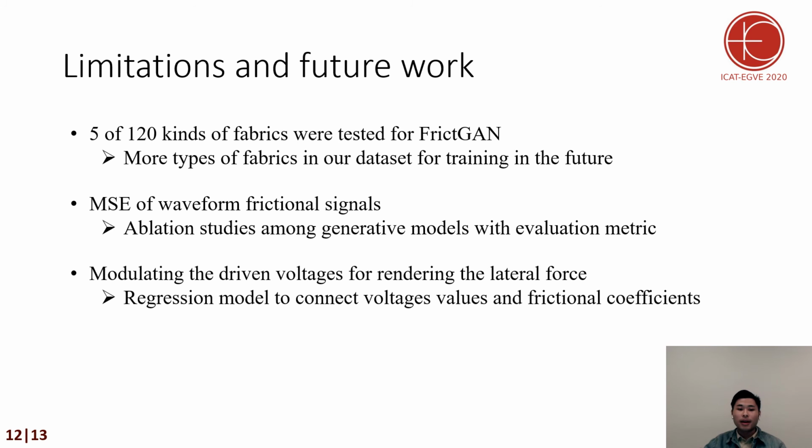Next, as electrostatic tactile displays need to modulate the driven voltages for rendering the lateral force, in our future work, we will add an additional data-driven regression model to predict the correlation coefficients between the driven voltages and the frictional coefficients. This is to render high-fidelity tactile feedback for the virtual fabric surfaces. Therefore, we will also conduct user studies to collect user subjective ratings on the realness of simulated textures.